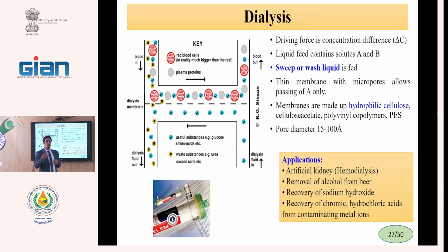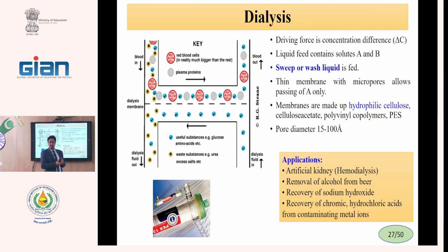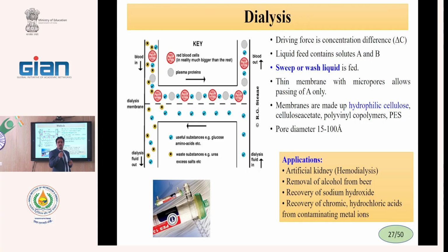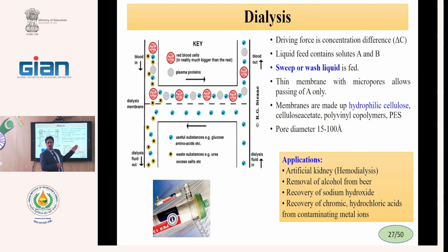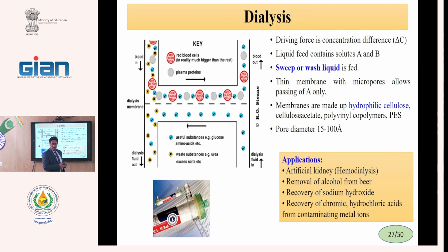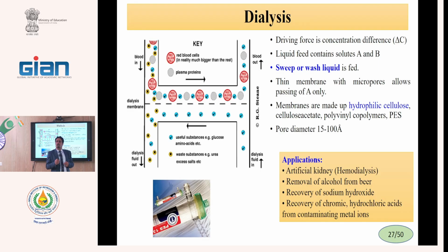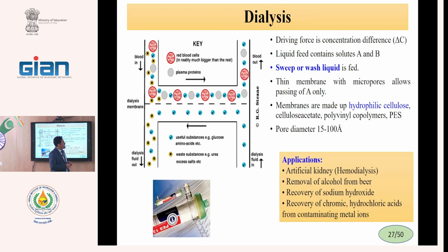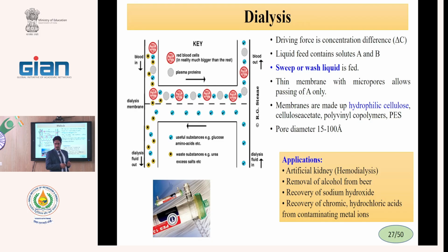We can use an ultrafiltration membrane as a dialysis membrane, with similar pores. But in UF, we apply pressure on the feed side, while in dialysis we have no pressure. The pressure of the feed and permeate side is similar, okay? No pressure, but we have a difference in concentration, and we have a difference in size of the molecules.